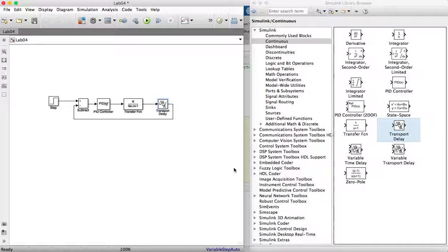Let's go extract the information from our simulation by sink blocks, so we may use this in our lab analysis. This is where the sink category comes into play. A sink is any tool that allows data extraction from a Simulink system to either work within MATLAB or display it to the user in some meaningful way.